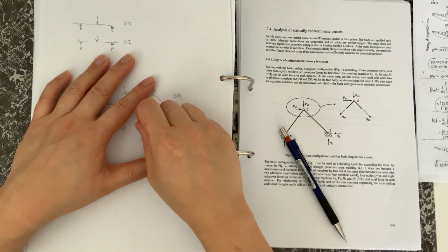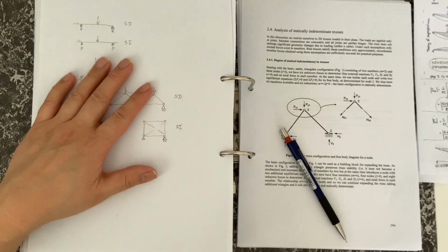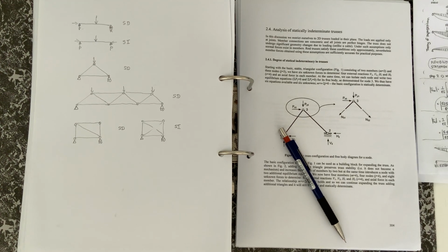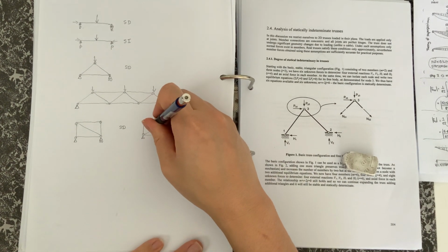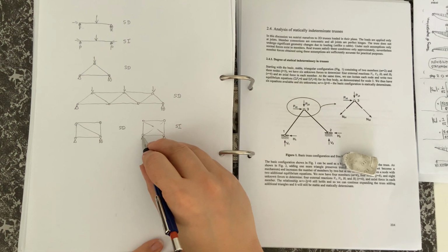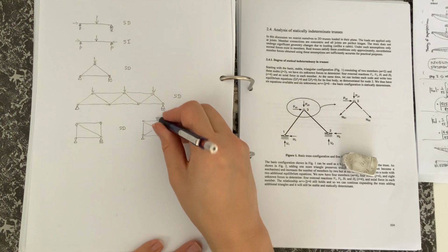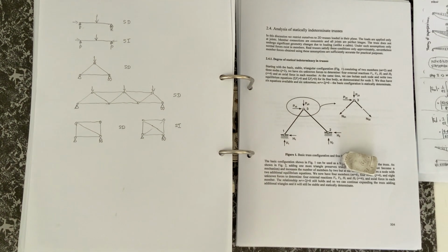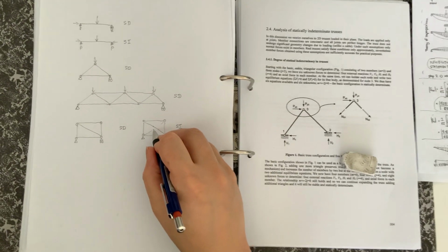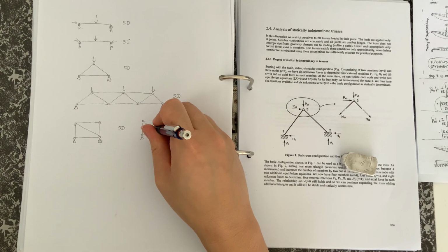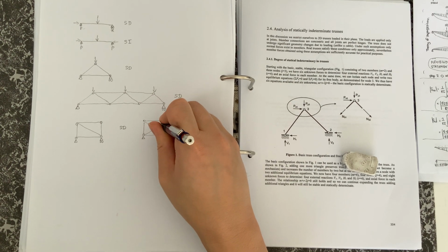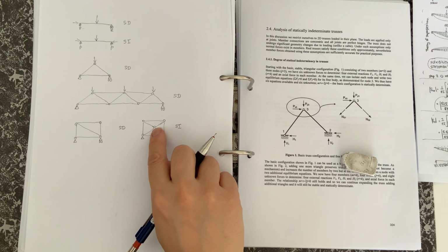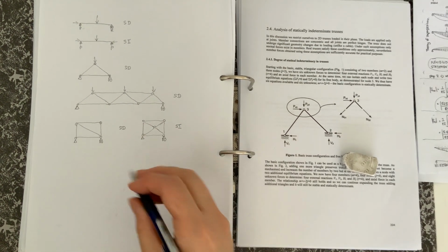Sometimes these might be two flat plates of steel, so they could be rubbing between each other. Just to be really clear, or sometimes they can just be two bits of string. It's actually tension-only bracing, so sometimes it could be just two bits of string or wire, and suddenly you've got a statically indeterminate problem. So sometimes it's drawn like that to indicate that it's not another pin.